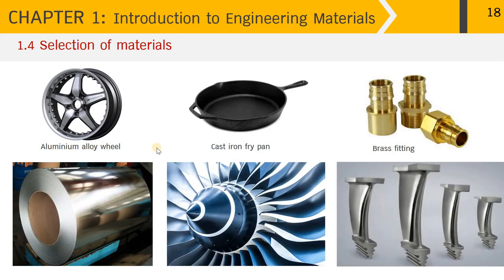And I'll lead you through three more samples. The first one, maybe not quite recognizable, is the zinc coated galvanized rolled steel that's made for forming to produce beverage cans, for example. And the second one in the middle here is made from titanium alloy for fan blades. And the last one is the turbine blade, which is subject to quite high temperature, over 1000 Celsius. And the metal to serve this function is nickel-based superalloy.